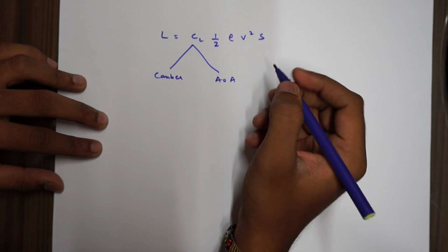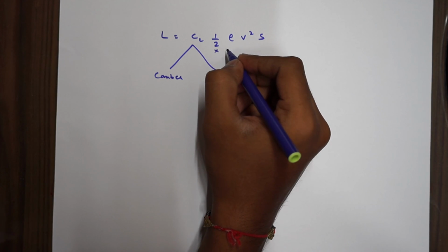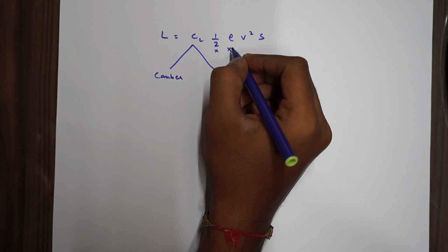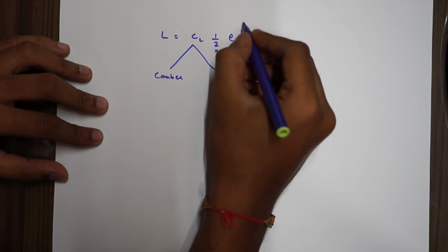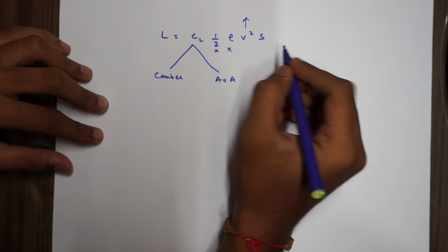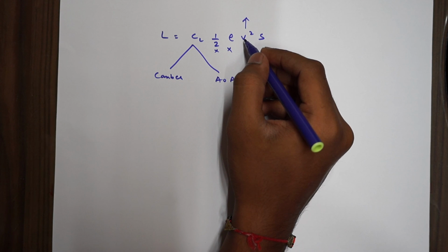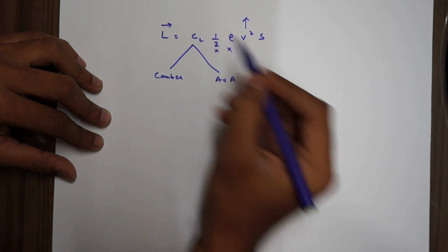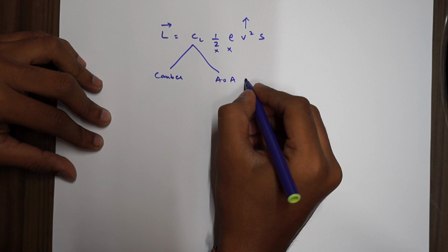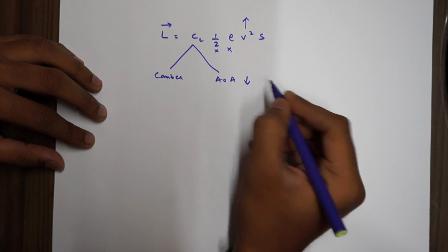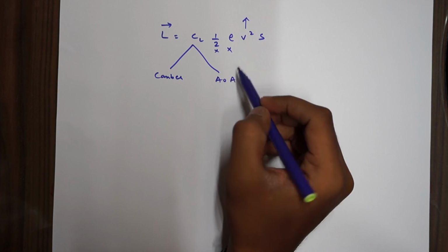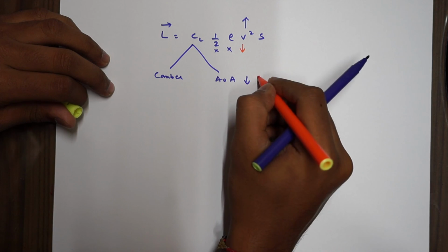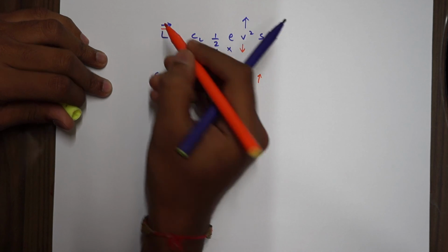And angle of attack. So in this case, at a fixed altitude, where the density won't change, if speed is increased or decreased, whichever, if the speed is decreased at a constant altitude, then to maintain constant lift, the angle of attack has to change. If you increase speed, your angle of attack has to decrease. And if you decrease speed, your angle of attack has to increase to maintain constant lift.